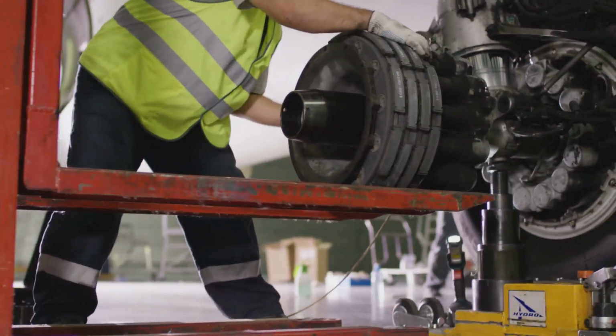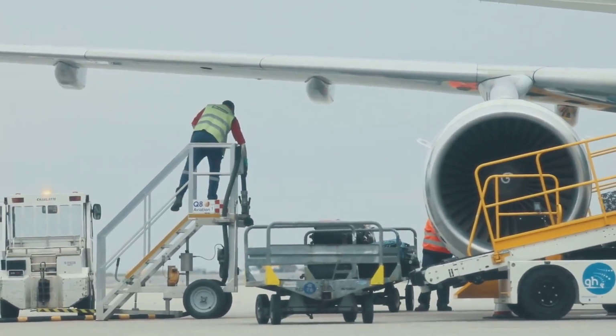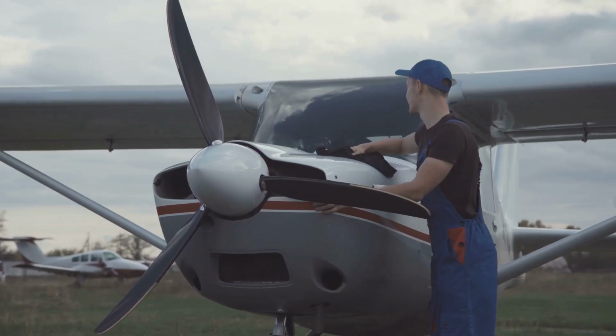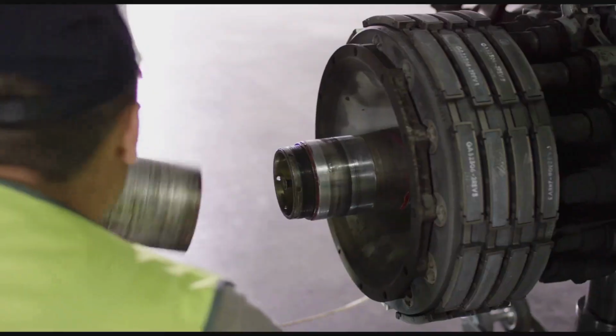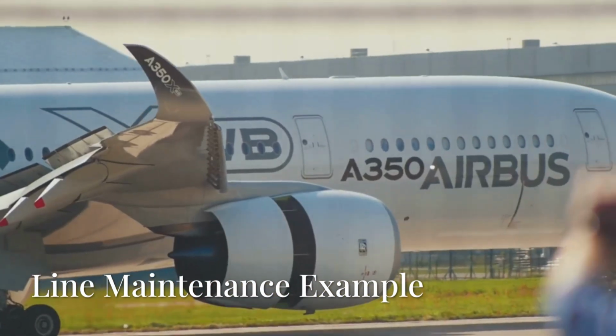Line maintenance is the day-to-day frontline care of aircraft. It takes place at the gate or on the apron, wherever the aircraft lands, and includes things like routine checks before and after flights, also known as transit checks, minor repairs, for example, replacing a brake unit, and component replacement under MEL, or Minimum Equipment List guidance.